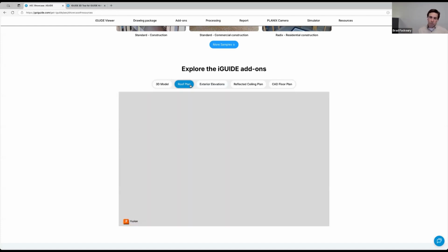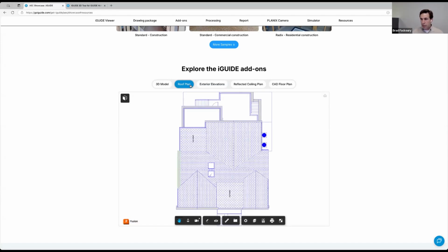Our roof plans, traditionally we get a lot of these on commercial projects. It's both flat roofed and pitched roof. This, along with exterior elevations, requires the vertical scanning, where we're picking up vertical data to help us draft and accurately represent the elements at the different heights. As you can see here, we're indicating pitch, the different sections of the roof, and penetrations if it's a commercial project. These are great for pre-construction site surveys, where you need a full evaluation of roof conditions and potential risk items.